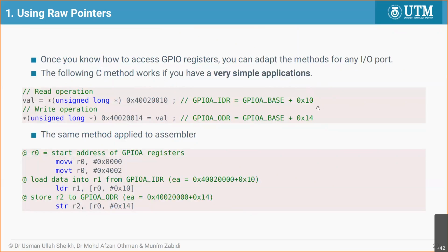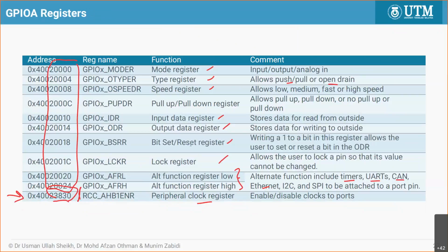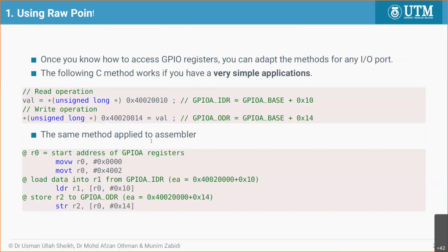What you do is you find out the exact address of the register and you write it down in C directly. For example, I want to access IDR and ODR. Looking at this table, IDR is 0x40010C08... in the slide, IDR is 400 210 and ODR is 400 214. If you want to make it slightly readable, you can use a macro, maybe define, but let's say you just want to be cruel to yourself. You want to use pure numbers. So in C, you can just do this.